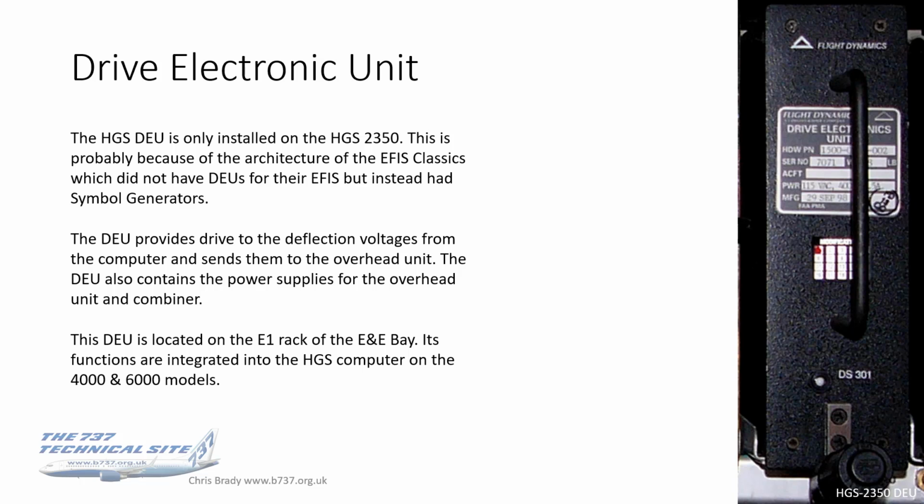And this is basically there to provide drive to the deflection voltages from the computer to send them to the overhead unit. It contains power supplies for the overhead unit and the combiner. Probably the best way to think of what the DEU is the graphics card. So for those of you that have had a go at making your own computers or speccing them, yeah, the DEU is effectively the graphics card of the system.